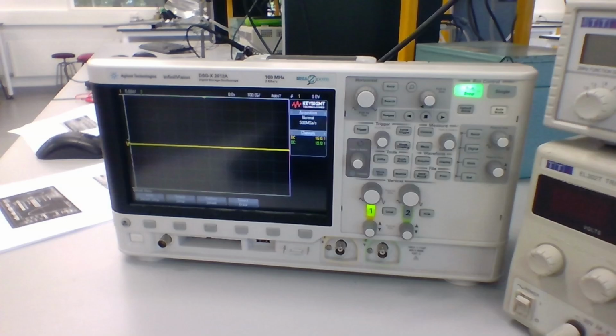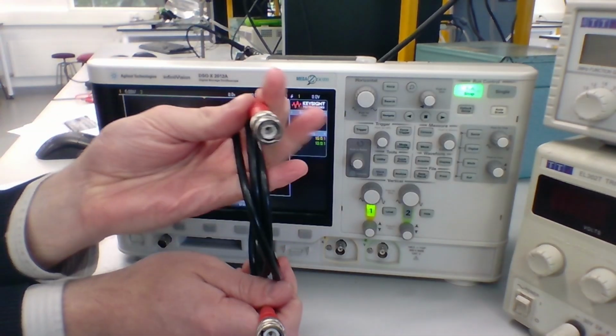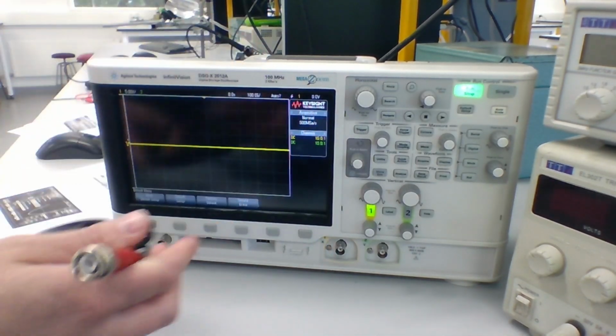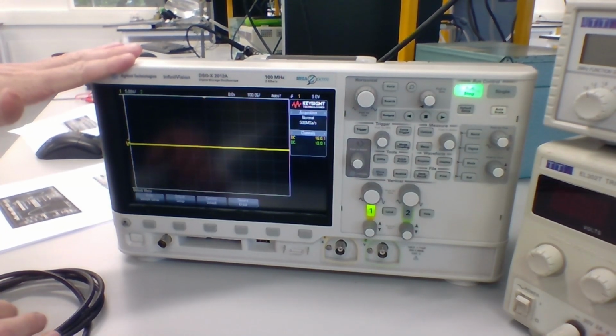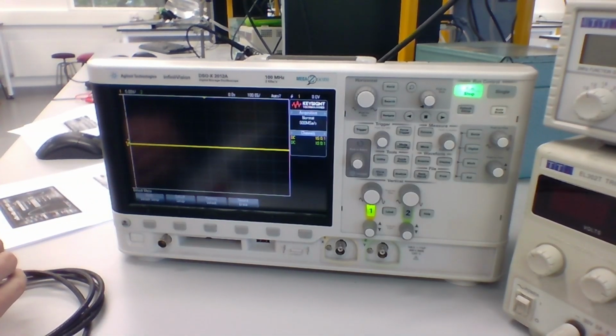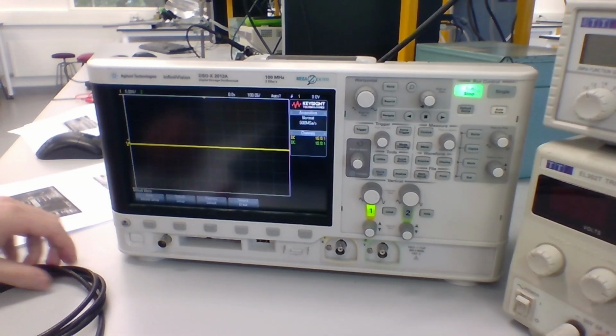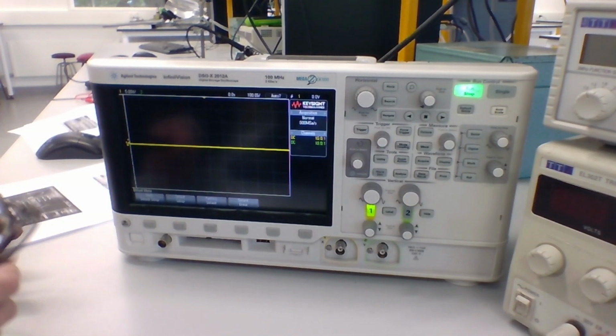What we're then going to do is take what's known as a BNC to BNC cable, which looks like this. So there's a BNC connector on both ends. And we're going to use that to connect the wave generator output of the oscilloscope back to one of the terminals to probe with. The instructions tell you to go and change the probe attenuation factor. I'm going to skip that for now so you can see what effect it has if we don't do that, and then we'll set that properly as the instructions tell us to.